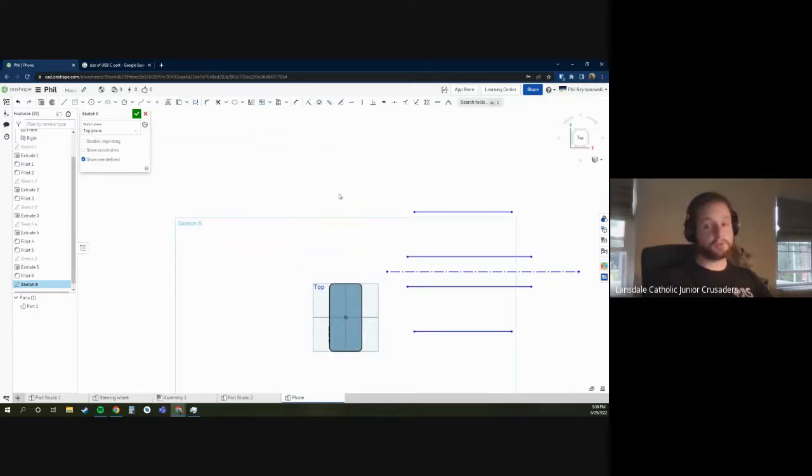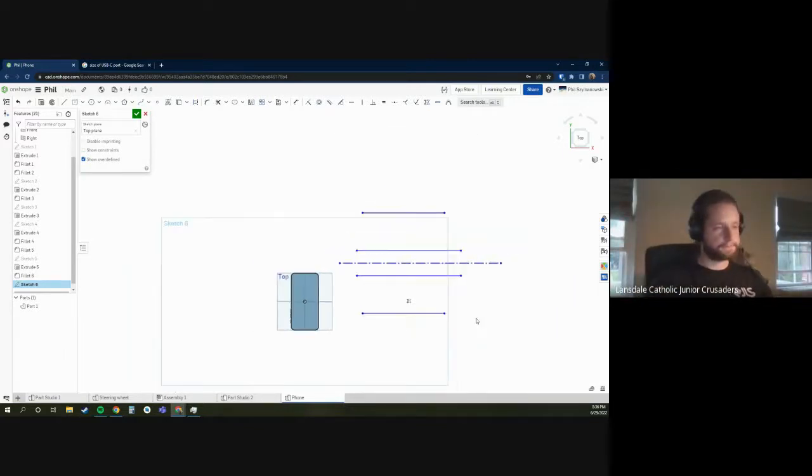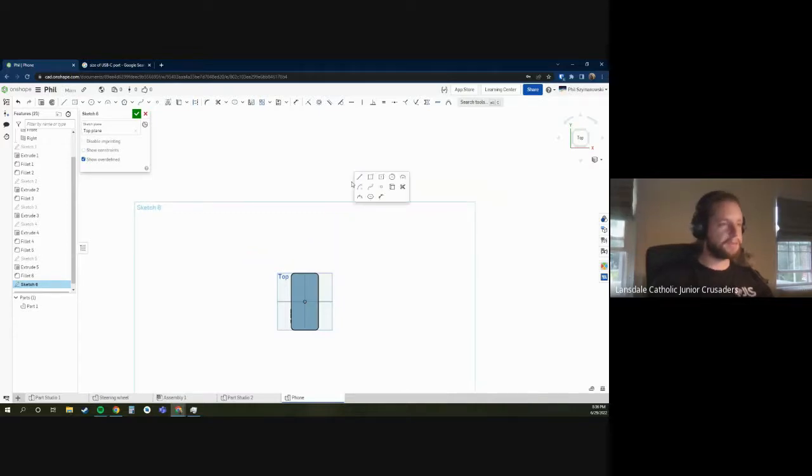You could also try to just sketch the one side and actually mirror the feature that you make. So when you extrude, when you either cut or extrude out, you could mirror that feature about some plane in the center. And that might be the way to go. But that slot feature is super, super useful, and there's so many things you can do with that shape.